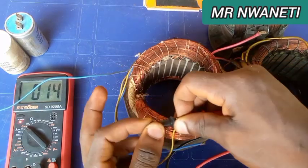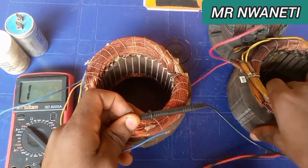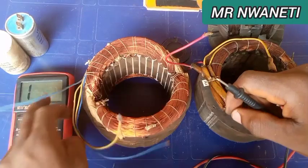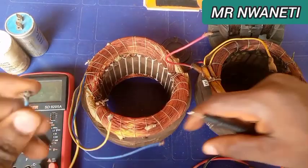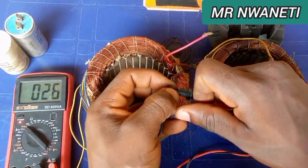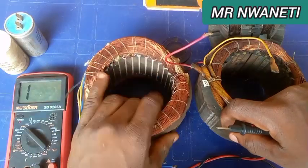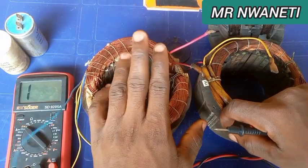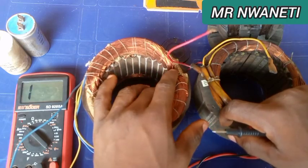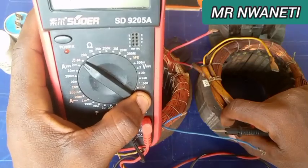You can see. Remember, this unmodified stator gave me, I think, 8 ohms, but this one displays 14. Okay, now let me read it from the mains. So the last time I used this stator, I generated almost 700 volts. So I quickly removed it because my meter's maximum output on AC is 700.